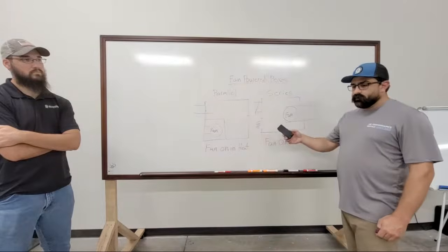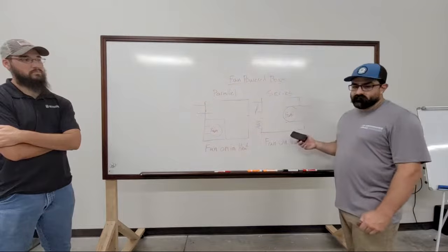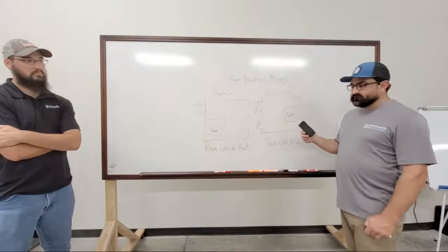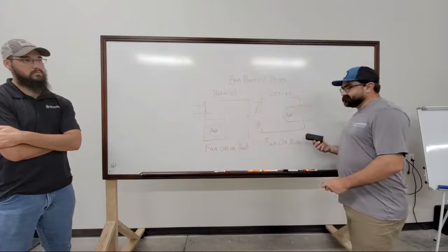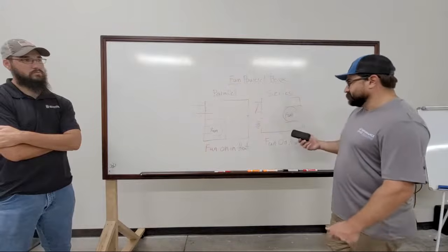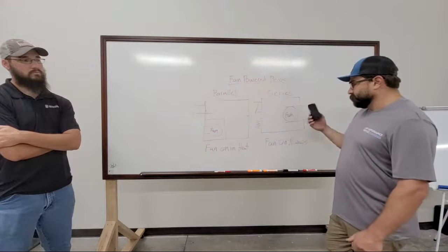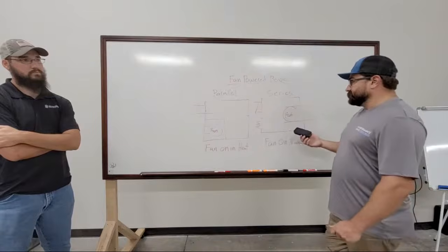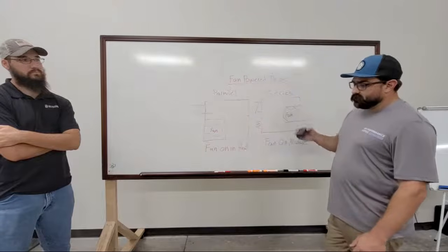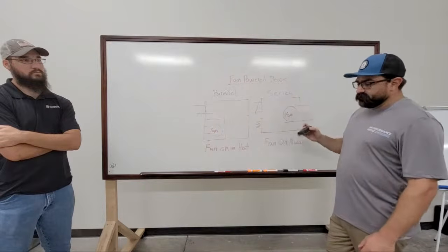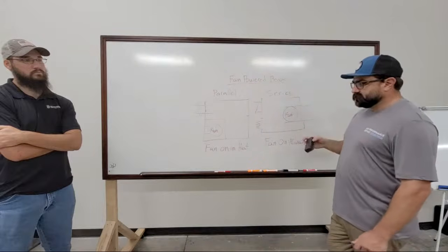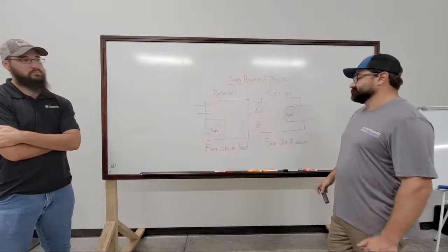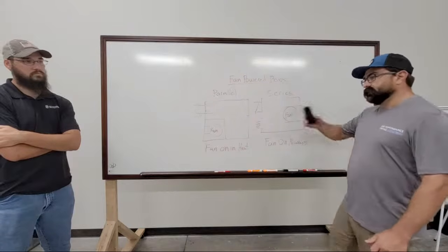So you kind of get a pull-through effect for airflow as well as the supply air. Like I said, I'm not an electrician. I don't know how that works with the amp draws and whatnot, but that's at least what I've been told by an engineer: they can have a smaller horsepower fan for a given CFM with a series design system than a parallel design system, because you shed your load down to the fractional motors.